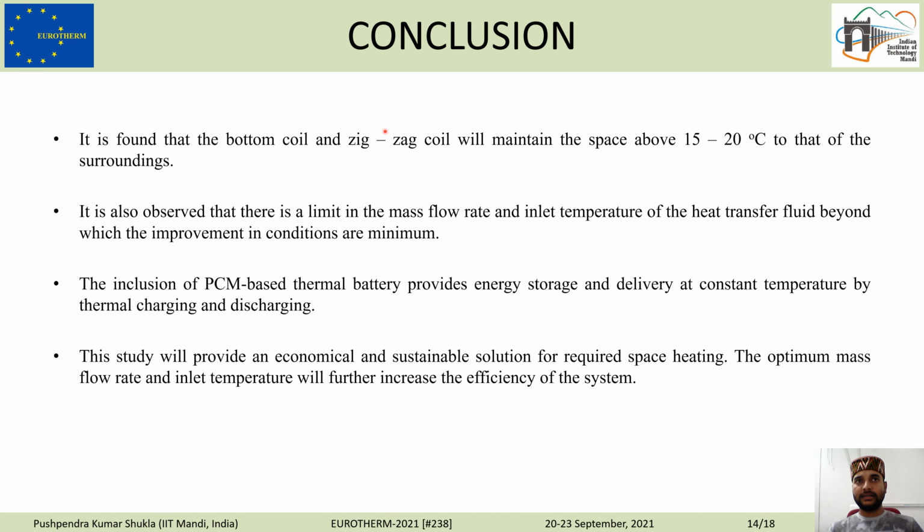From this analysis we had concluded the following things. It was found that the bottom coil and zigzag coil will maintain the space temperature 15 to 20 degrees Celsius above the ambient. We already saw the effect of mass flow rate and inlet temperature of the heat transfer fluid. After a certain limit, the change of mass flow rate is not giving that much energy change inside the dome.